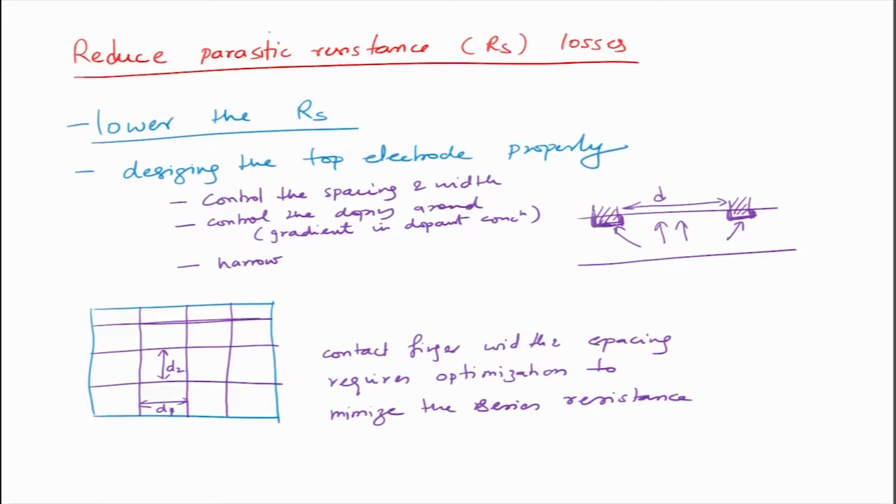They are narrow on top, but they are buried, which means with high depth. So, they make a good contact by going deep into the N layer, but their spread on the top is low. Okay. So, if you look at the top view, this is low and this is high. Okay. And this is extremely important to improve the charge collection.